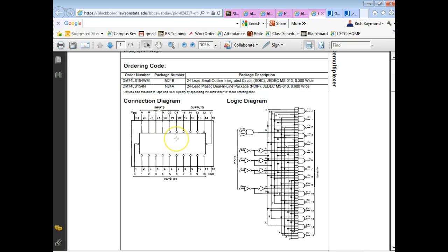These 2 guys are low active. So you can see right here, to make any of these NAND gates over here work, this right here has to be high. Can you see where the enables are connected to all 16 of these NAND gates over here? So if this output right here is low, then all the outputs are going to be high, no matter what's on the input.